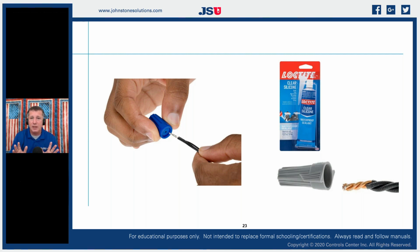So whether it's solid or stranded, we're going to cut off existing wire nuts. We're going to re-strip those until we get good clean copper. We're going to pre-twist them together. We're going to put those inside of a wire nut until we get them nice and locked in, and then we need to fill those in.